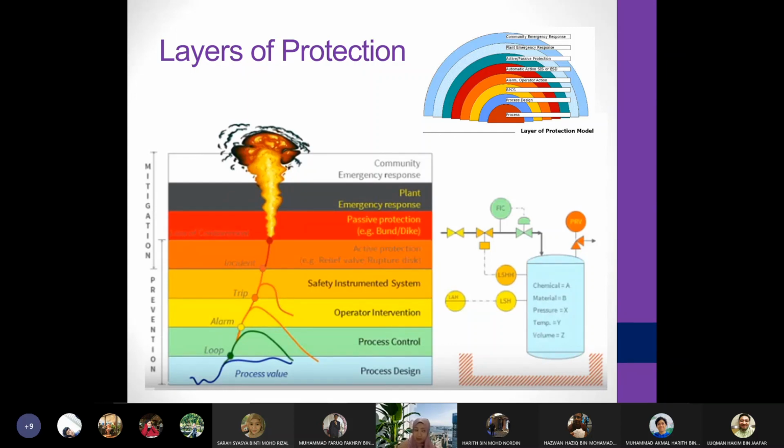So you have that rupture disc. If you remember that demonstration about the BLEVE demonstration, when you have that tank and it's being heated and it causes the rise in pressure in that tank, it has that rupture disc. So the rupture disc releases the pressure, so that you don't have that increase of pressure in the tank.